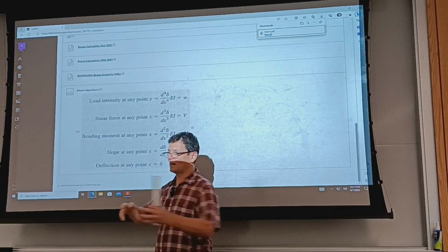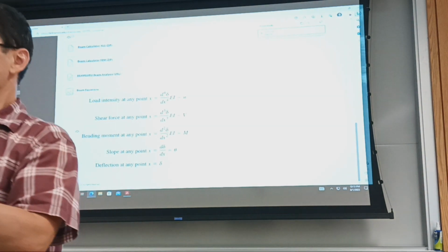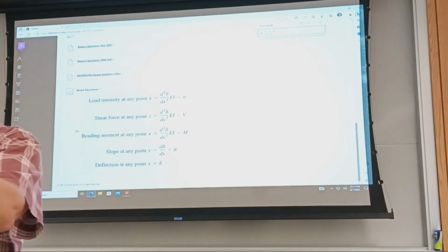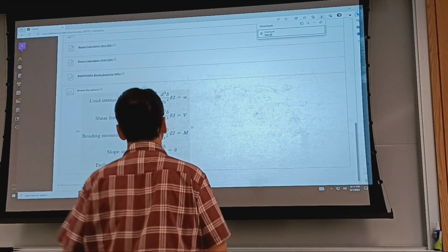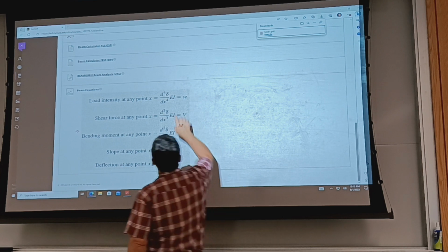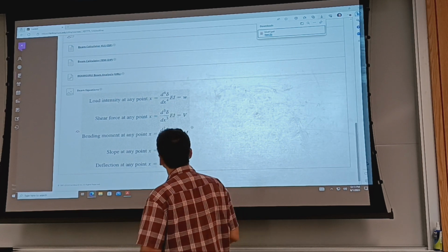So stepped shafts, fabricated beams, and you see this commonly with areas that were reinforced. You have a plate that you welded where loads are applied to help with delivering of the load in that location. But you also add to the geometric stiffness of the beam.